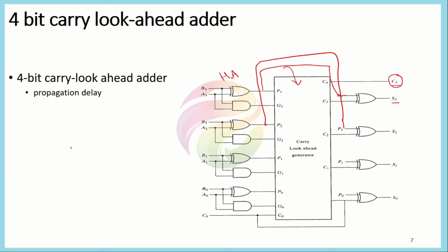If you remember, if you use the full adder in the 4 cascaded form, then we ended up with a 9 gate level delay at that time, and we assume that each gate represents a unit delay, so there was 9 unit delay to perform the full addition process. Now we will look at how this look ahead adder is useful in reducing this computation time.